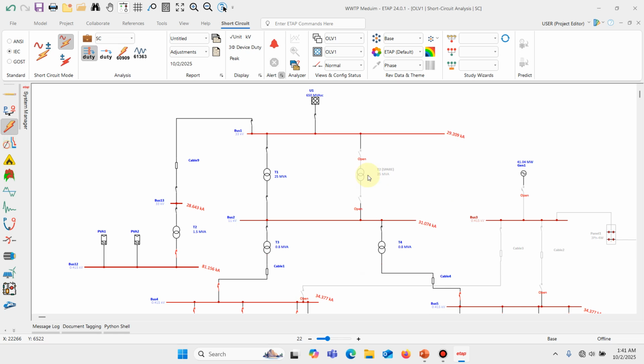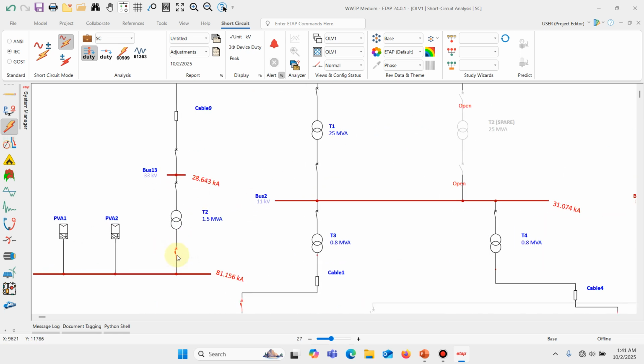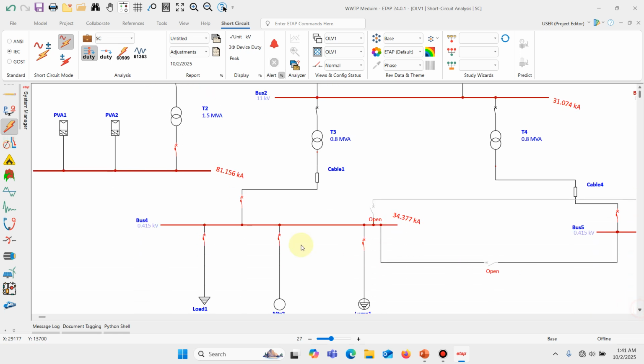No guessing, no assumptions. For example, we can see over here this breaker, let me zoom in. This breaker is flagged red. This breaker is not flagged red. This breaker over here is flagged red, meaning there's a problem. We go down, let's see other parts of the system. These breakers are flagged red, meaning we have problems. So we can identify these problems even from the design stage. Without implementing it, we can see that these breakers have problems, we need to work on it.